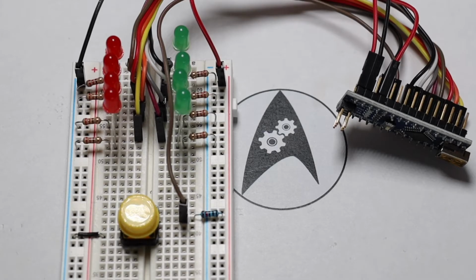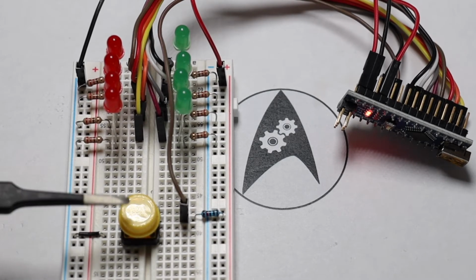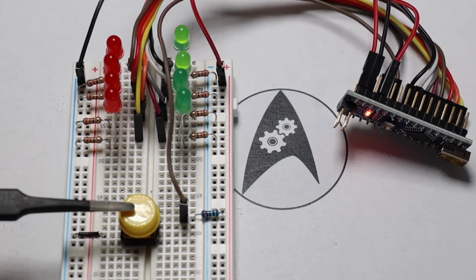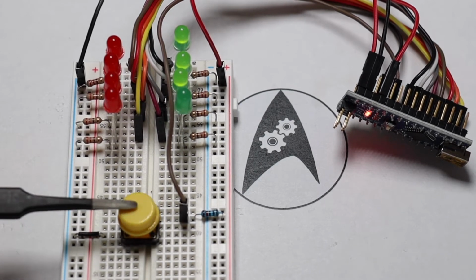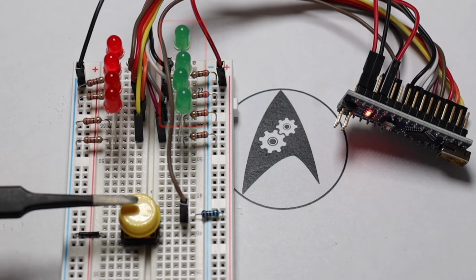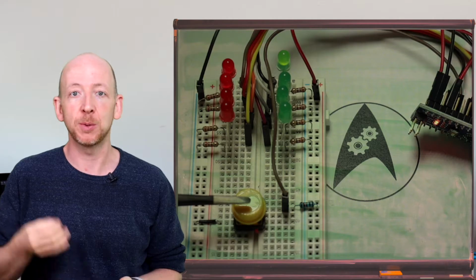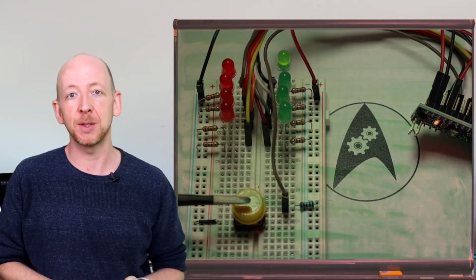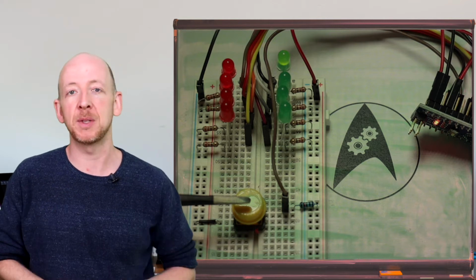But let's now power up the circuit and do some counting. And you can clearly see that for each time that I press the button, another LED lights up, just as in the simulation. But once in a while, the counter increments several steps at once, even though I have pressed the button only a single time. So clearly something in the circuit here is not working correctly that differs from the simulation we just saw.